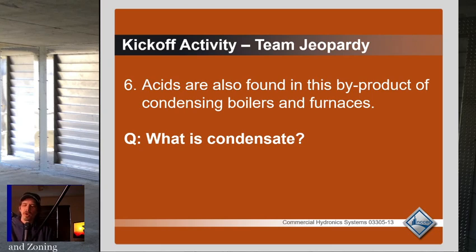And I think that's also a little overstated, because really if you're using plastic waste piping, there's really no reason for you to worry about the acidity of that condensate. As far as I know, I've never heard a good argument on why you need a neutralizer if that condensate's going to be entering a plastic piping system. But if it is entering a metal piping system like cast iron, or copper even, then that corrosive nature of the condensate can be an issue.